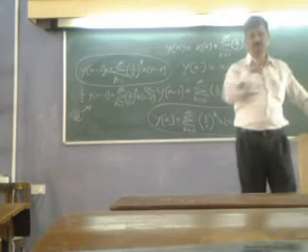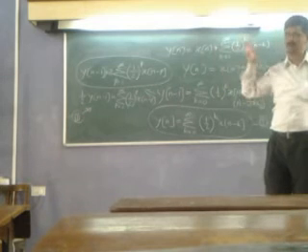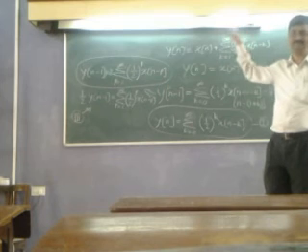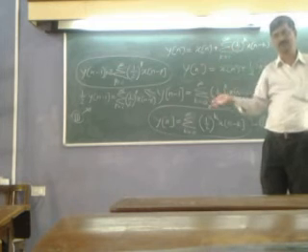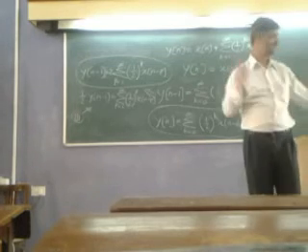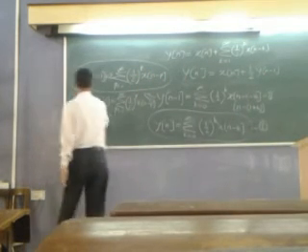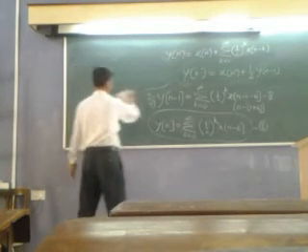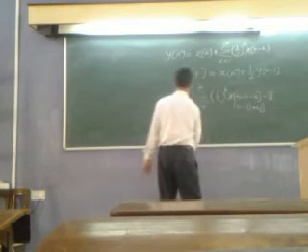So right now we have two equations, first and second. For both of them, we know xn, and the equation between yn and xn. We also know hn. We also know that our output is equal to the convolution of xn and hn. We will find the Z transform and try to interrelate how it fits. So Z transform, inverse Z transform. We will try to present a near complete picture. So two cases we are considering: one is called infinite impulse response and the second is called finite impulse response.